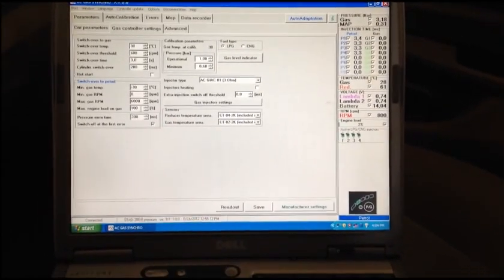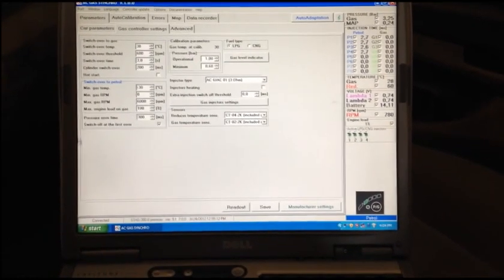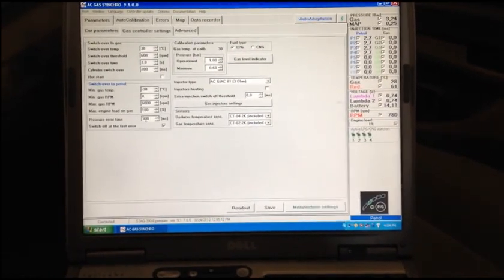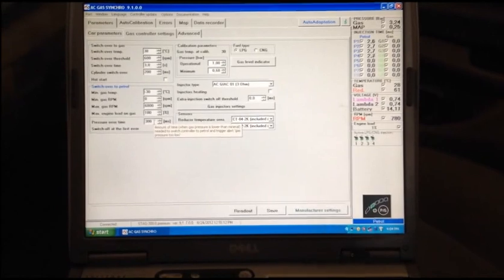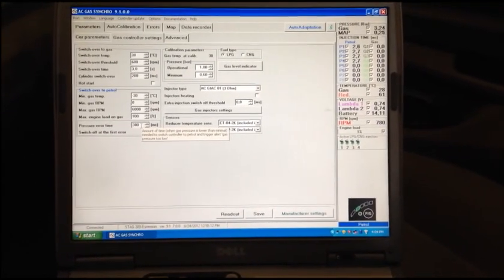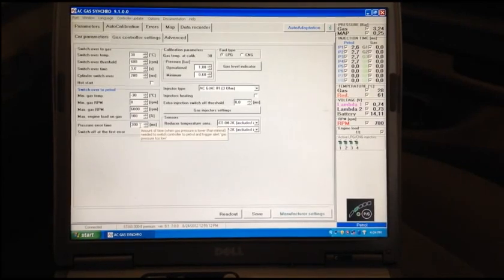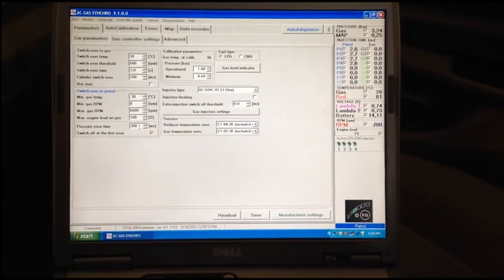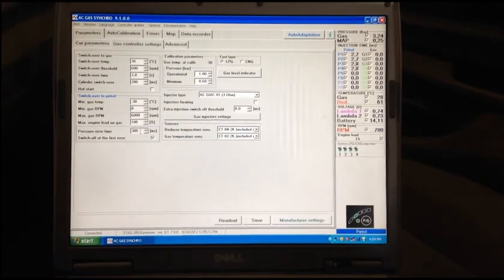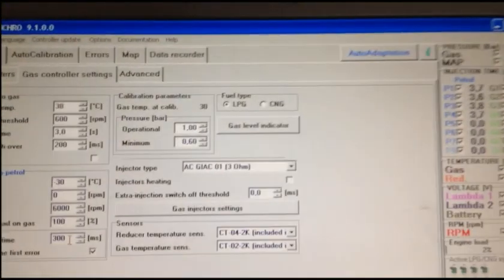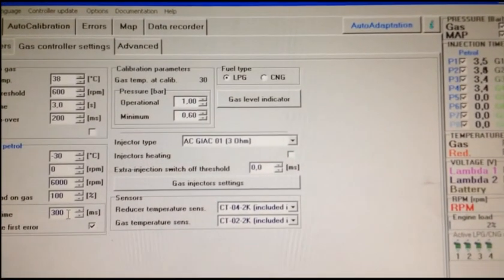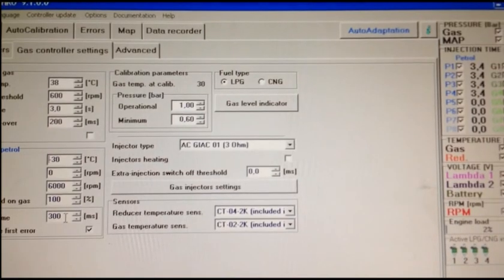Now the pressure error time below that is the time difference that occurs whenever you have a dip in the pressure settings, that it falls below your predefined minimum CNG pressure on the rail.